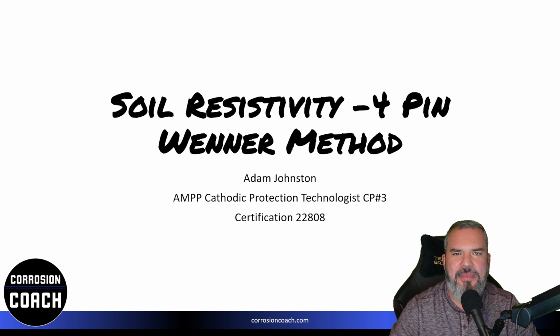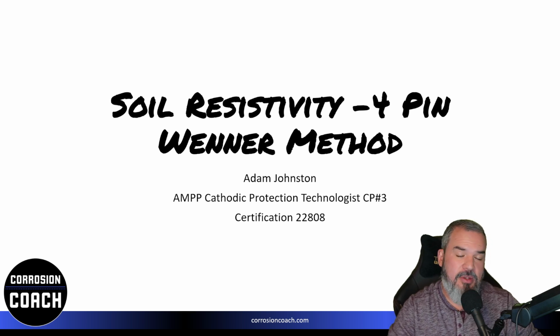Let's get huddled up. Today's practice, we're going to talk about soil resistivity, and we're going to talk about the 4-pin Wenner method. Yes, that's how it's sounded out. It's W-E-N-N-E-R, but it's Wenner, to help obtain soil resistance measurements, and then we're going to calculate resistivity together.